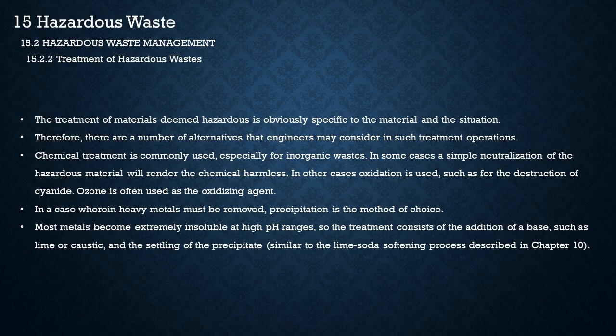15.2.2 Treatment of hazardous wastes. The treatment of materials deemed hazardous is obviously specific to the material and the situation. Therefore, there are a number of alternatives that engineers may consider in such treatment operations. Chemical treatment is commonly used, especially for inorganic wastes. In some cases, a simple neutralization of the hazardous material will render the chemical harmless. In other cases, oxidation is used, such as for the destruction of cyanide. Ozone is often used as the oxidizing agent.